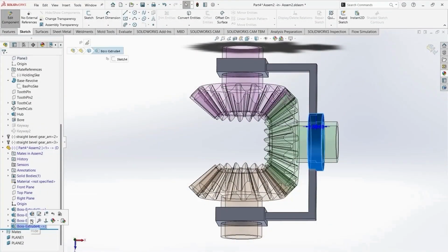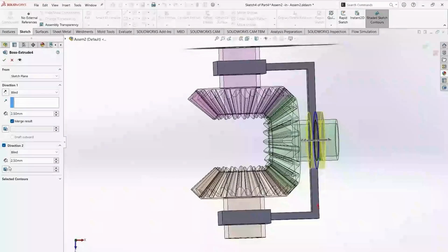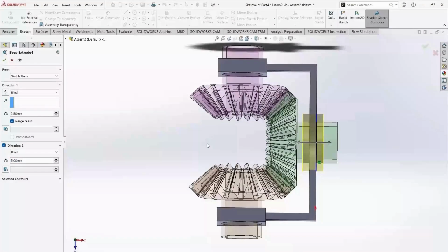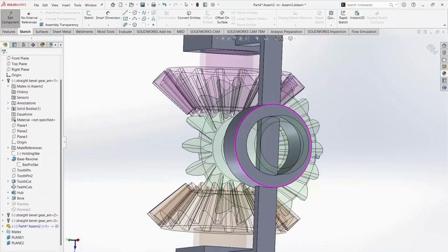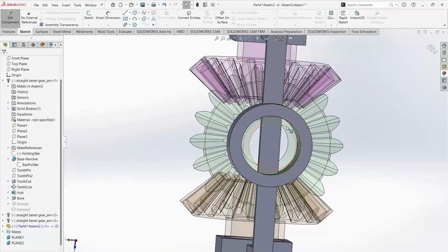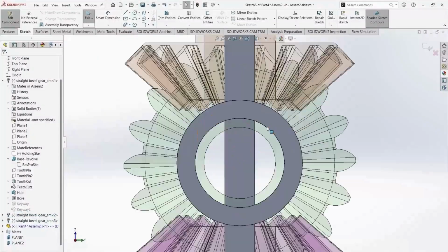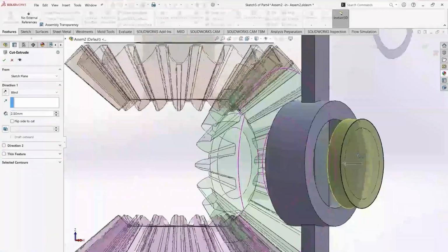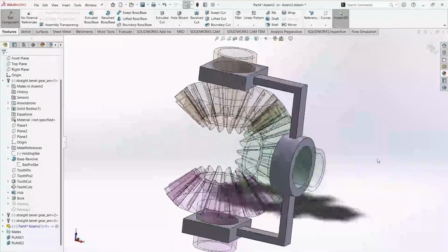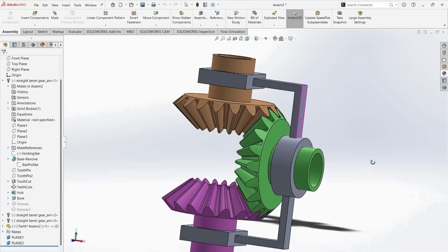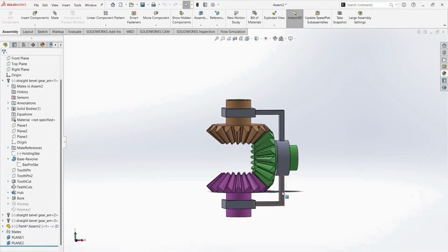Now again go to the bottom extrude. So your bottom, make it not 2.5 but 5. So this looks more better. Nice. Now what we'll do is again select this face, click on sketch, select this convert entity, features extrude cut, and make it through all. That's it. Okay. Now just click on exit part to see this part have been made.